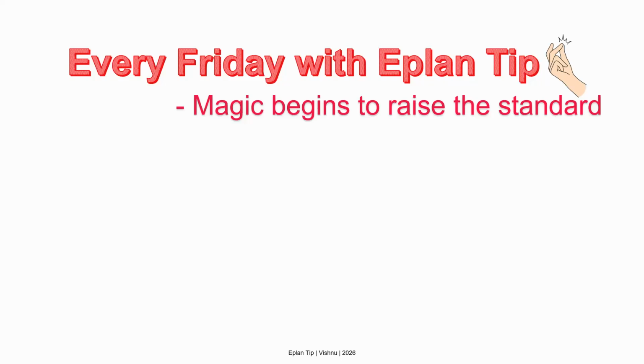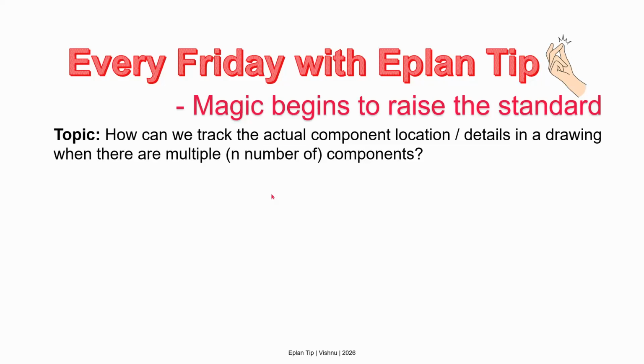Today we are going to check on that actual component. Like for example, if I have a breaker, a contactor, or a PLC, in the drawing, where all is it used? Sometimes it can be on different page types like the ORU page, multi-line page, or single line page. Or sometimes, in the multi-line page only, the same component will be on different pages. So how do I track those things?